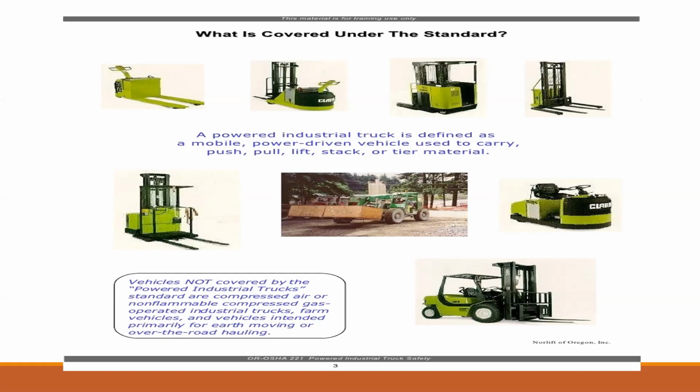And this charging area is also a very hazardous area because high voltage sources are there, which means the sources of ignition are there. Sometimes if they are not using dry batteries, they have the normal acid batteries, so there are vapors coming out when the battery is being charged. So this becomes very dangerous, and we have seen a couple of accidents in the battery operating area.